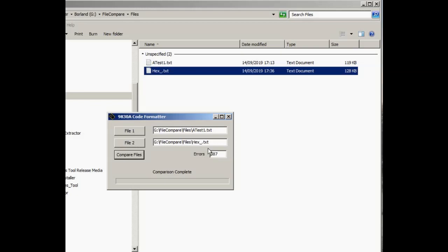If the code will not work in the emulator, then again I can have a reasonable degree of confidence that there is indeed at least one failed ROM in the ROM board. In which case, as you know, I'm making a replacement ROM board, and I can then just use the data from the emulator to program the ROM on that board, and in theory the machine should work, at least as far as the code is concerned, and it will just be a case of dealing with any remaining hardware issues.